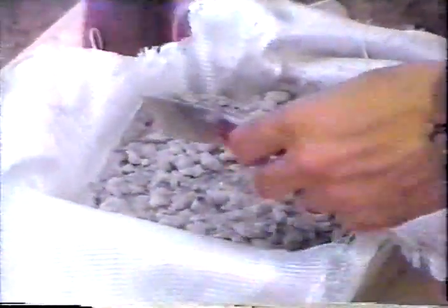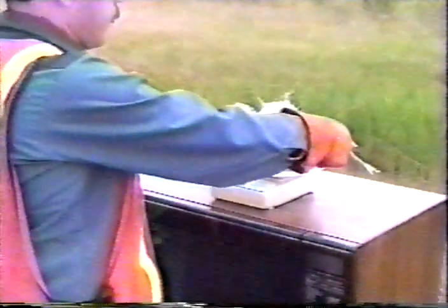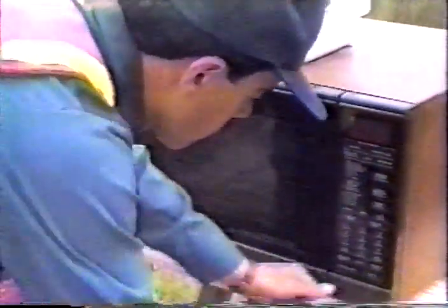It's stirred with a scraper, wrapped again, and then weighed. This dry weight is recorded as WD1. Next, the sample is dried again, this time for 2 minutes.